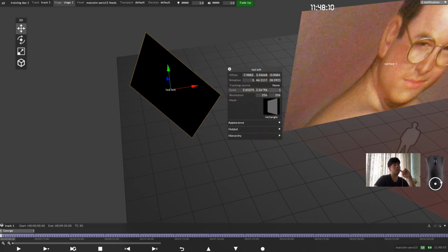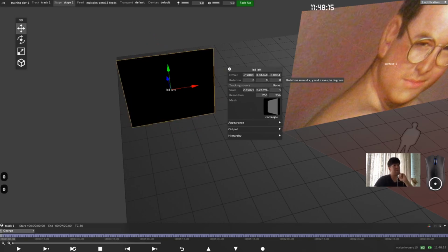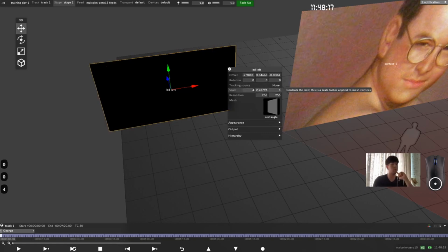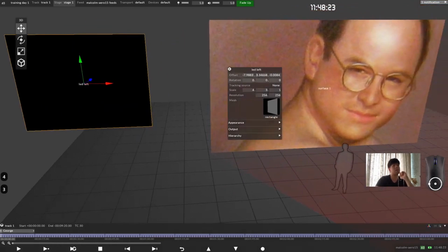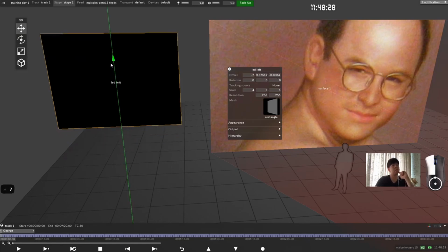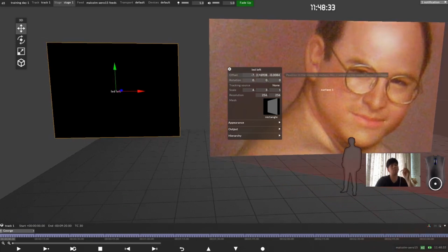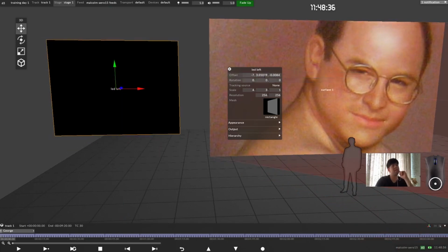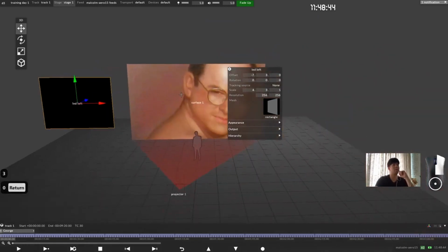Right, so I just want to remove the rotation. My scale, I'm going to do a 4:3 screen. Then set the position to -7 meters. You can use the gizmo to move around, so no issue, but I prefer to make it more precise, so I'll always do a fixed number. Then your Z is 0. Right, so I have my LED left.